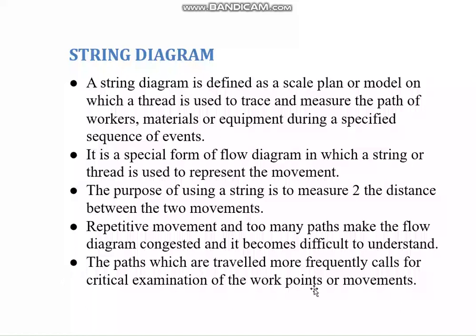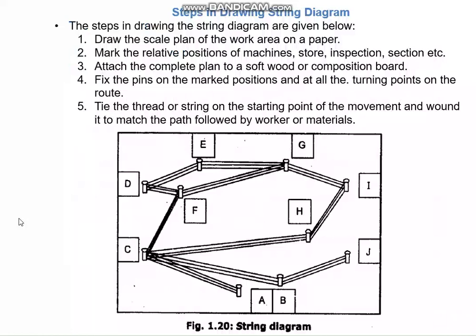See, the paths which are traveled more frequently call for critical examination of the work points or movements. If a lot of thread is wound between two points, then we can give attention to that. We can critically analyze it, because if you can bring those two points together, you will be able to save time. Okay, let us see how the string diagram works.